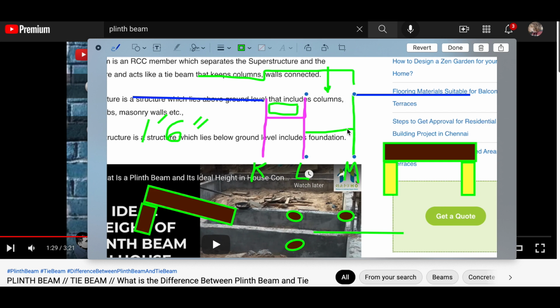Of course here, this floor level in here, keep this in mind. This is 1'6" over here, from the deck to here, 1'6". But from here, we're at 12'9". 12'9" to 1'6". We have even a smaller plinth beam dimension. This is 1'6" over here, but over here, our internal floor is still at 13'4", I believe. 13'4", and we're at 12'9".